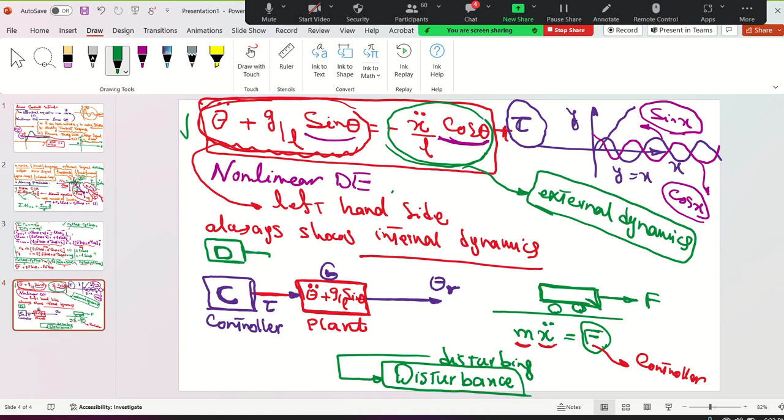So you see, guys, there's no magic. I'm just following this differential equation. The disturbance is being subtracted from the controller output. So you have to have a sum, like the sum operator in Simulink. Here is plus, inside here is negative. So tau comes here from the controller, and the disturbance is being subtracted from that. Here we go. And the result goes to the robot, the moving robot or moving pendulum. Are you following me? Yes, everybody? It's just like playing with blocks, like at a high school level.